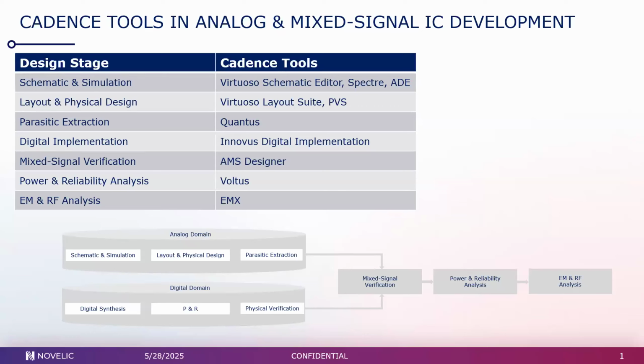Also, one very important next step is parasitic extraction. And Cadence has had this feature for a very long time. It's called Quantus. After the layout phase, we can extract parasitics from the layout. These parasitics can include the resistance of the wires and the parasitic capacitances, and usually this is what is extracted, but Cadence also supports inductance extraction, and that is very important.